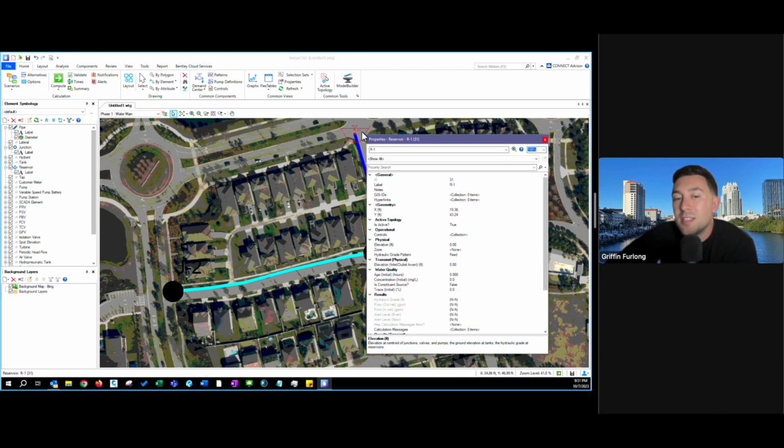So in order to set a static pressure, I need to set an elevation to this reservoir. Now, in order to go from PSI to feet, you can multiply by 2.31. So if I had 50 PSI, let's say, we get 115.5. So now the system's going to have a static pressure of 50 PSI. And you can even leave notes in there: elevation equals 50 PSI. I really like to leave breadcrumbs for my team, especially after I build these models, because that's a really big assumption there. Now, I am totally fine with how this thing is operating.